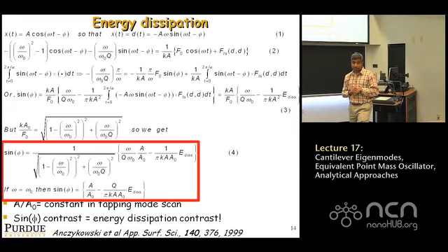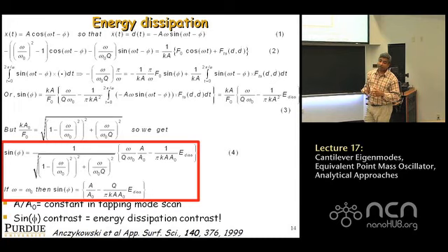Okay? So that entire term in the integral is actually the net work done due to dissipative forces, or the energy lost due to dissipative forces in one cycle of operation. Because if the interaction forces are purely conservative, that integral must be zero, because in one cycle of operation it has to be zero.